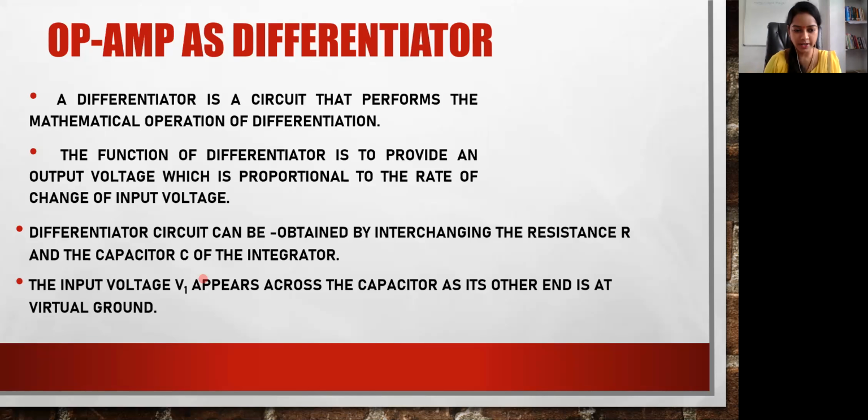That's why it is written as dV/dt of whatever we have at the input terminal V1. This is called a differentiator. So how are we going to design it using an electronic component? Just connect a capacitor over here and you will have a differentiation of the input voltage.